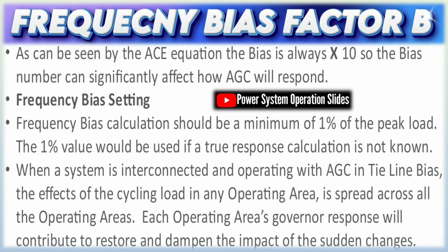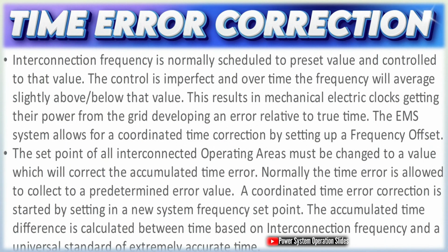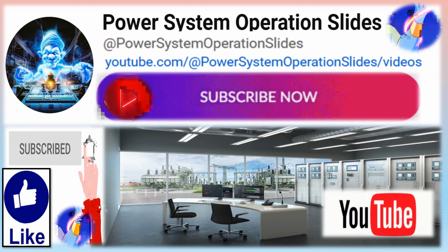Constant net interchange: this operation concept establishes that the net power exchanged over the tie lines should remain at a predetermined value. Even when local load demand changes, the interchange is held constant by adjusting the generation accordingly. Maintaining constant net interchange is essential in interconnected systems, ensuring that power trading and contractual obligations between regions are respected.